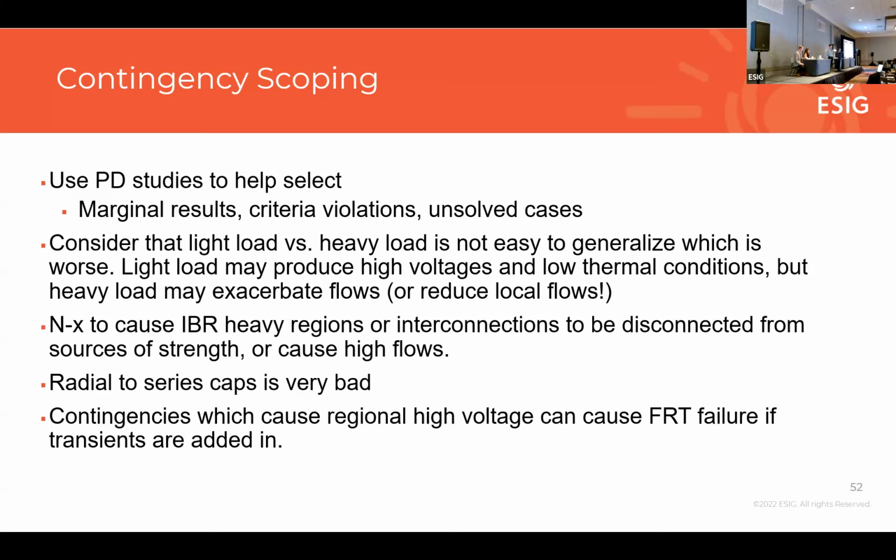And a note on the dispatch scenario or load scenario that you want to study in EMT. We can't generally say that, for example, a light load case is going to be worse than a peak load case. They're essentially different things that you're going to see in those cases. In a light load case, you're more likely to have higher voltage transients, as transients aren't necessarily damped by a lot of load in the system.